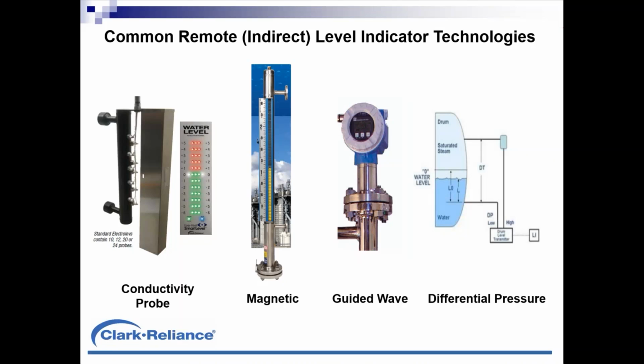The third type would be a guided wave level transmitter. We'll call this the newest technology that's evolved into the marketplace. And these can work quite well in the application and be designed appropriately for the various pressures of the applications. While there's nothing in the code about mixing technologies, obviously many would agree that if I mix technologies, even using the last type, which has been the most common for many, many years now, differential pressure transmitters,